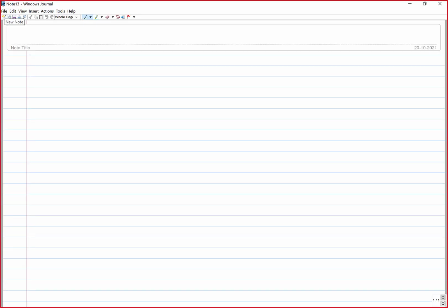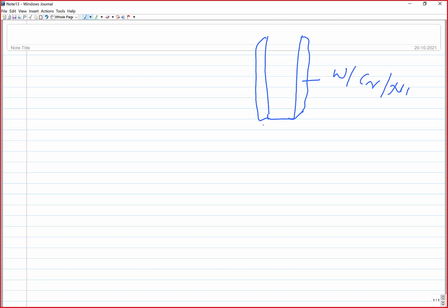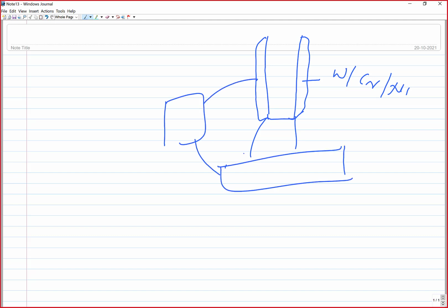Then the important role performed by these coatings is that if you want to add certain alloying elements, like say this is the core wire, and you want tungsten, chromium or nickel, then you can simply add these alloying elements with the flux itself, with the coating. So we can say that controlled alloying can be achieved using the flux coatings.